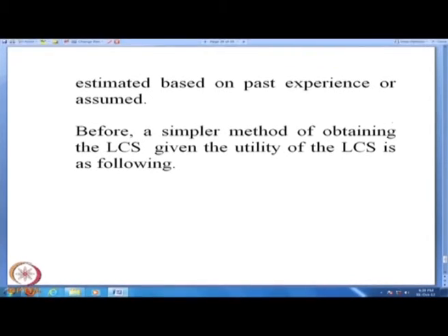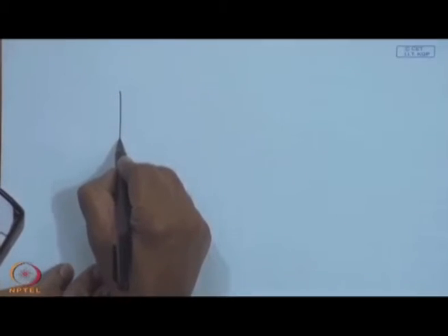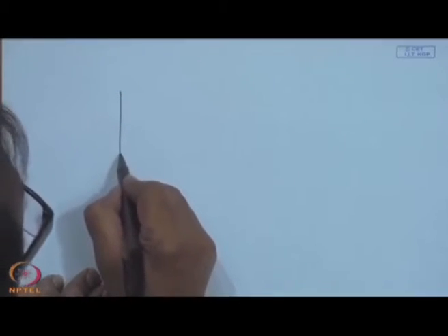life cycle savings, right. Suppose we have got the method to calculate the total net savings over a period of 20 years, assuming that the life of the solar energy system is 20 years. I have taken care of a possible scenario for the fuel prices, a possible scenario for the depreciation, a possible scenario for the degradation in the performance, etc., and obtained the life cycle savings. If I plot, in general, we may think that